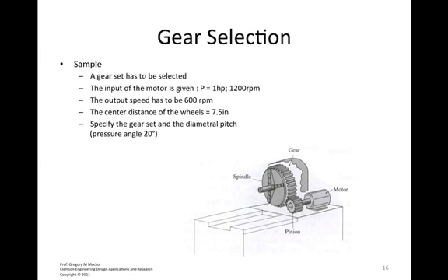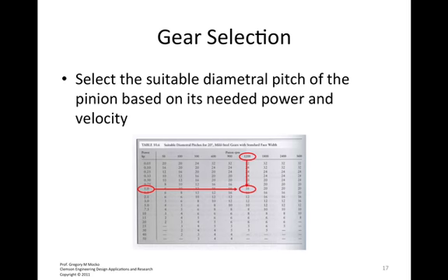In order to specify the diametral pitch, you would go to a gear manufacturer's website. That manufacturer is going to create a variety of gears based on different materials. They might be heat treated differently. They might have different tolerances. But you would come to a catalog like this, or potentially equations by the manufacturer, and you would find 1 horsepower.